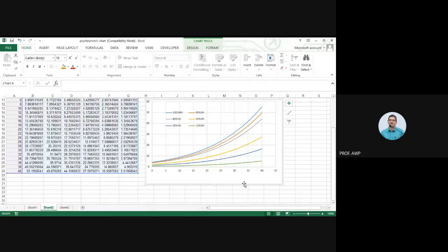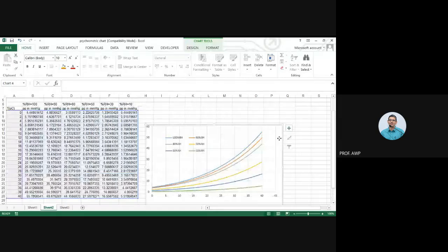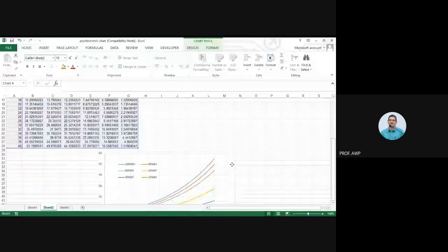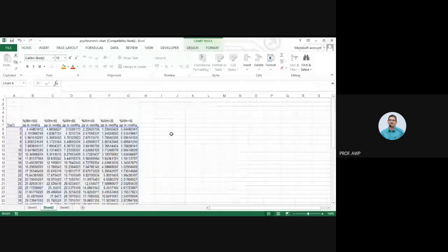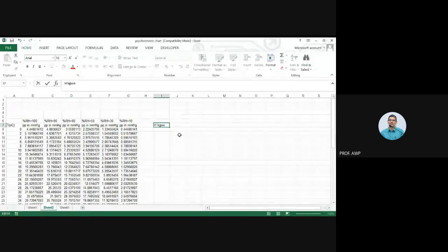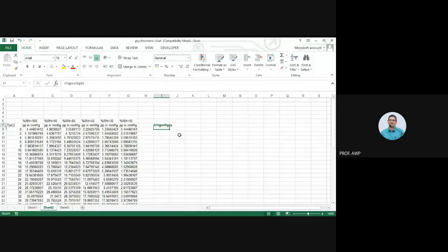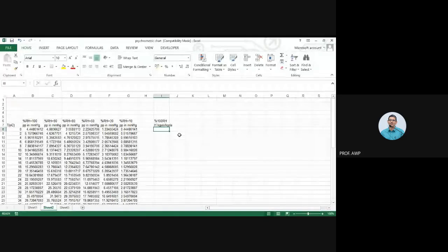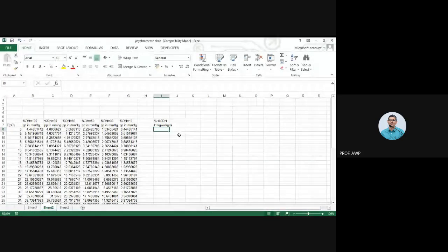or 0 to 50. Everybody has got up to here. Now we don't want partial pressure. Suppose we want it in terms of humidity. So if I want humidity in terms of kgs of water vapor per kg of dry air, and we want this corresponding to 100% RH, what will that be? Now remember, total pressure is 760 mmHg, right?